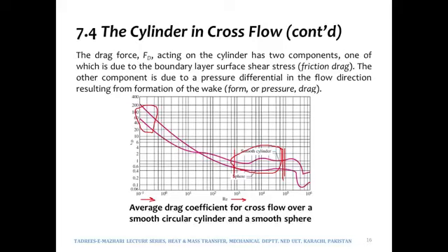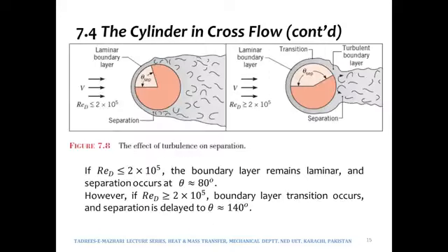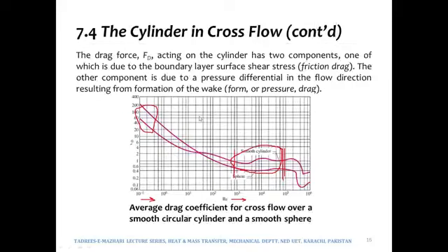So the boundary layer would remain laminar, but the flow in the downstream region, this region, right? This is the downstream region and this is the upstream region. So the flow in the downstream region would be turbulent. And of course turbulent means that would give rise to a wake region and flow reversal and all that.